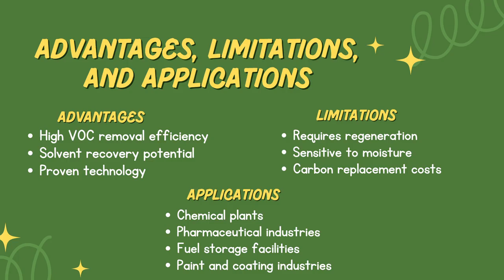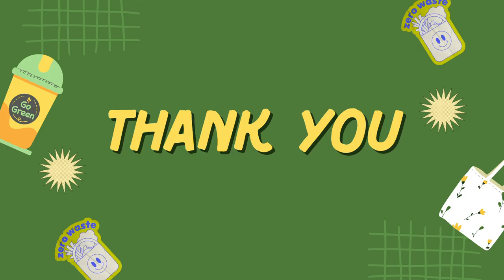So here are the advantages, limitations, and applications of carbon adsorption. The advantages are high VOC removal efficiency, solvent recovery potential, and proven technology. The limitations are that it requires regeneration, is sensitive to moisture, and has carbon replacement costs. And for the applications, it can be applied in chemical plants, the pharmaceutical industry, fuel storage facilities, and the paint and coating industry. I think that's all of my presentation today.